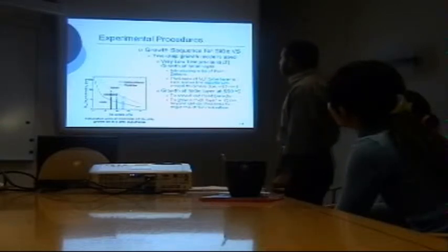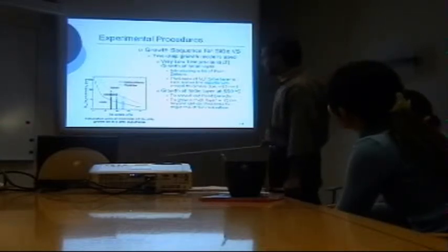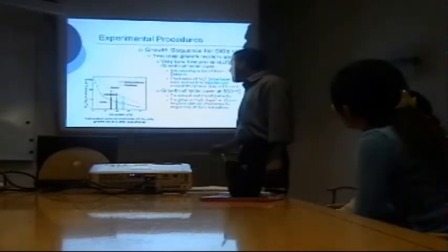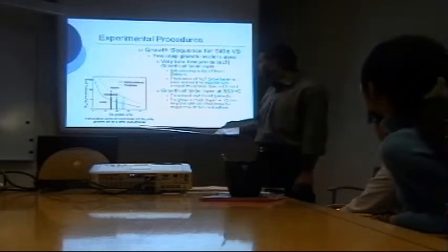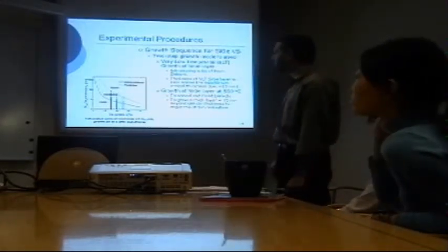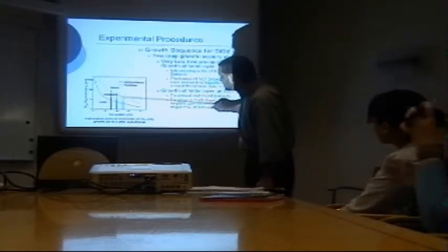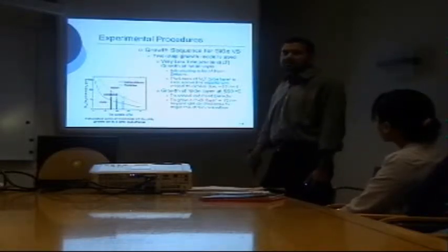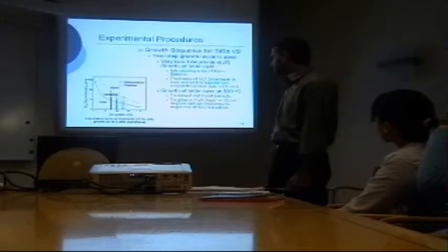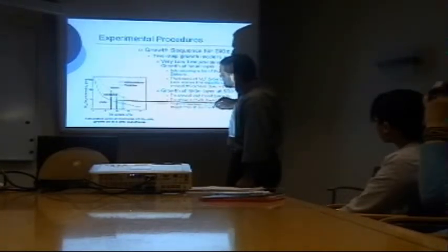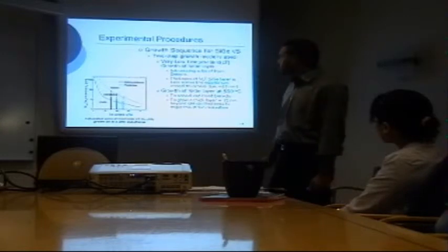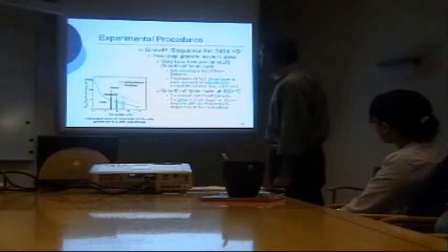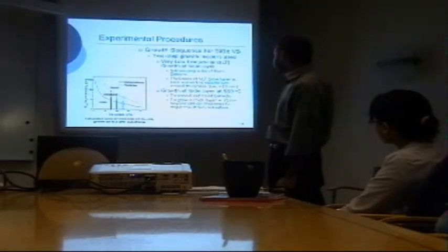The thickness values were decided on the basis of a theoretical model given by Matthews and Blakeslee, and People and Bean, which you can see in this figure, which shows the calculated critical thickness for silicon germanium grown on silicon. And we followed this in this project work because we tried to grow the silicon germanium with 40% germanium concentration. This black region represents the thickness for the very low temperature growth mode, and this line part represents the thickness in the high temperature growth mode.